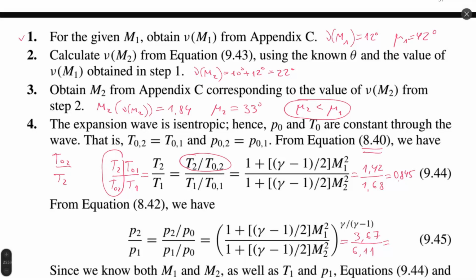As we remember, pressure changes most among the thermodynamic properties. Then we also have some considerable change of density, and the change of temperature is smaller. So the temperature ratio will be closer to 1 than, for example, the pressure ratio, which would be closer to 0.